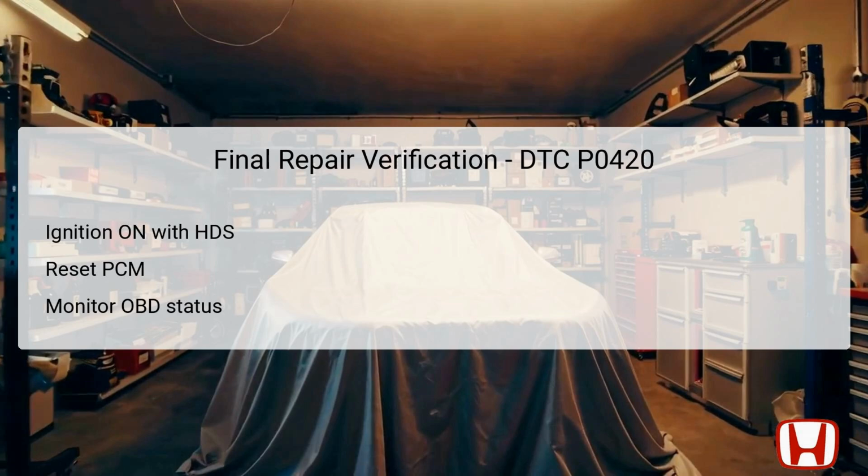Begin by turning the ignition switch to the on position again, or pressing the engine start button, stop button. Using the HDS, the Powertrain Control Module, PCM, should be reset to ensure it clears any old data and recalibrates itself with the new components if applicable. Following the reset, it's crucial to execute the PCM idle learn procedure. This helps the PCM adapt to the new engine conditions and fuel mixture settings.